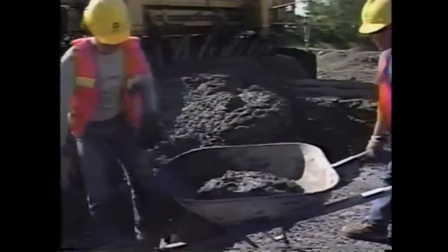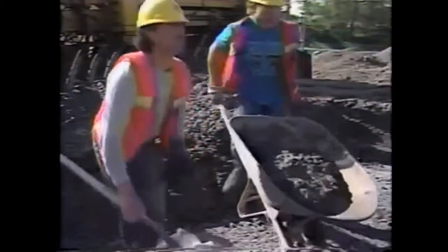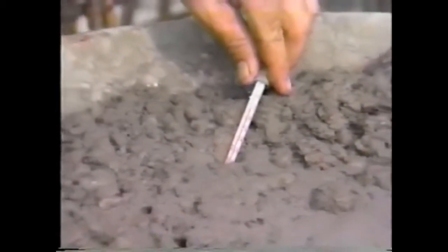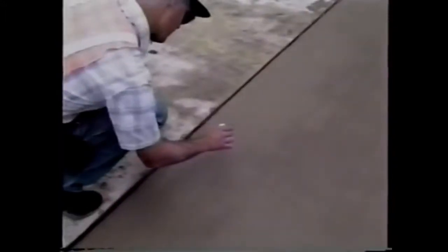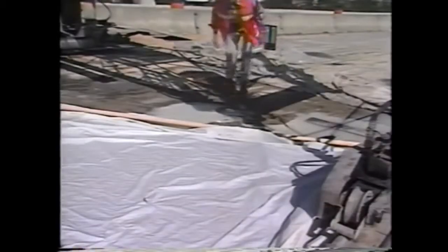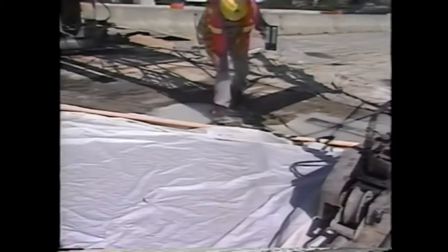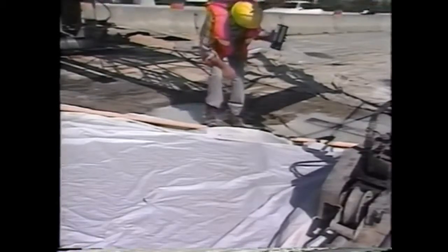The concrete should be gently pressed around the thermometer so that the air temperature does not affect the reading. The thermometer is left in the concrete for 2 minutes or until the temperature stabilizes. The measurement must be completed within 5 minutes after the sample is obtained. The temperature of in-place concrete is measured in the same way. Now, the air temperatures during concrete construction are also important. The high and low air temperatures must be monitored daily.